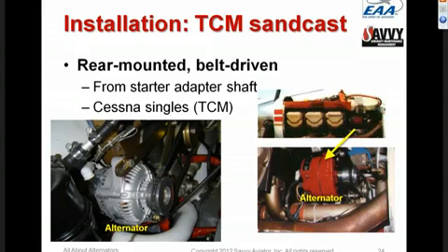So with these rear-mounted alternators, we frequently run into heat-related problems, premature failures caused by rectifier diodes blowing out because they're not being cooled well enough. And it's often necessary to arrange some sort of a blast tube to blow cold air on the alternator when it's mounted in this position.